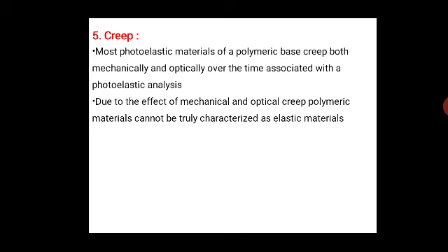Because of these effects of mechanical and optical creep, polymeric materials cannot be truly characterized as elastic materials, but must be considered viscoelastic for certain applications. One of the first attempts to formulate the mathematical theory of photoelasticity was made by Mindlin, by considering a generalized viscoelasticity model, which consisted only of elasticity elements with the shear modulus.